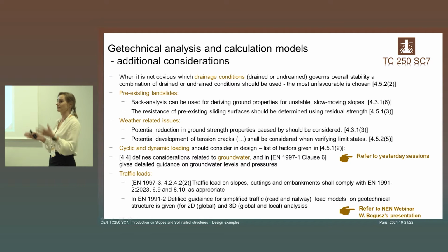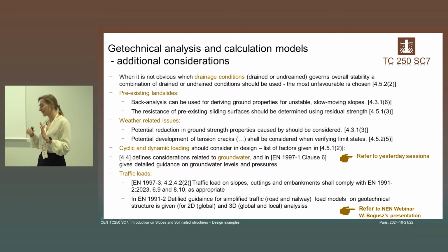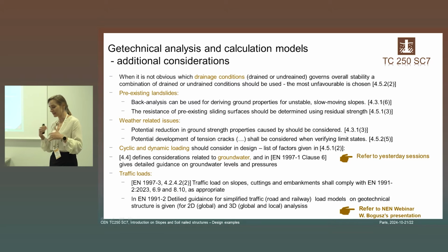And then some other issues, perhaps not directly in clause 4, but I found extremely helpful in Eurocode 7 Part 1, in clause 6: a very detailed guideline on how to deal with groundwater levels or pressures is given, because until now it was not so clear.